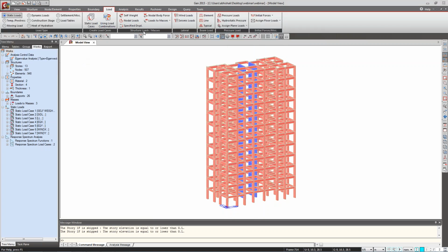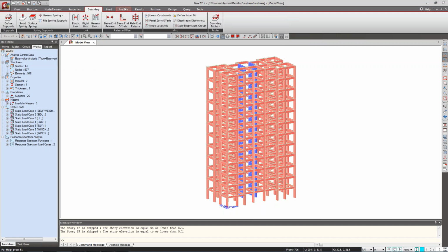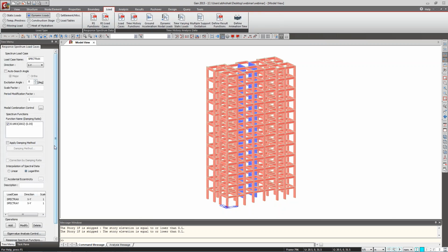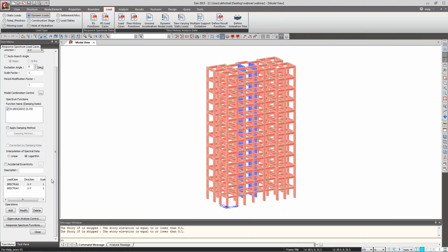The same value you can get for wind also. If you are satisfied with this option, you say okay. Now in the analysis, the dynamic load, RS load: in the RS load, we cannot define the additional forces. For additional forces, you have to manually input the data. So in the dynamic analysis, we cannot increase the dynamic load floor-wise.